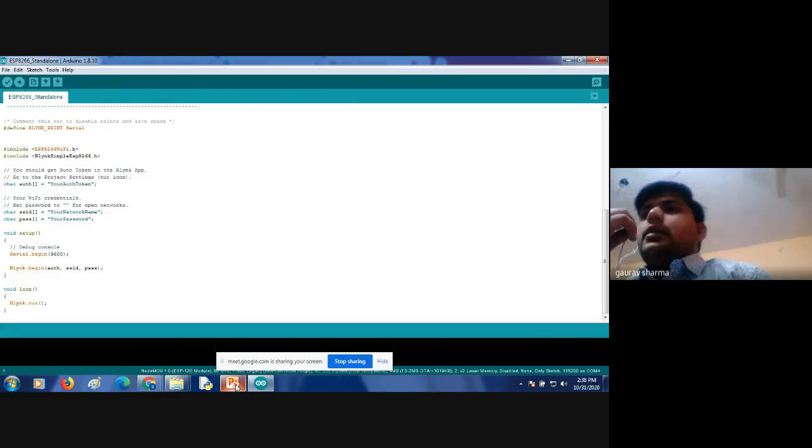Like we have the temperature sensor LM35, suppose. When you make its circuit and interface it with any development board, such as the Node MCU development board, it gives you the output from 0 to 5 volt.